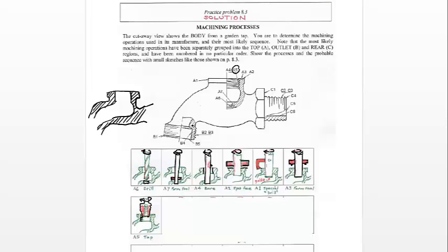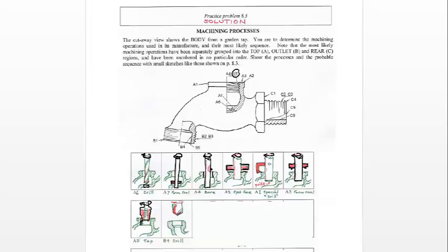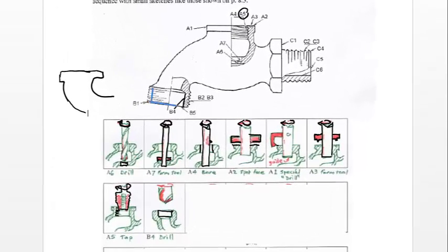Next we move on to part B, which is this outlet. We are going to be doing the bottom part. So first of all, you are going to have to orientate the outlet in this way so that we can do the machining processes. The first step in B is drilling. So you draw the drill for the radius of this hole. That's B4. Next is B5.